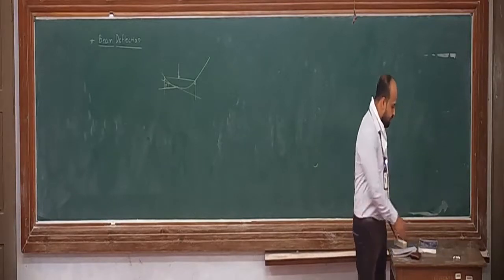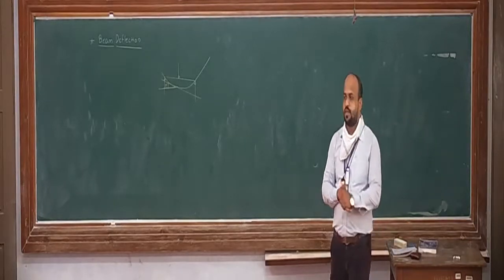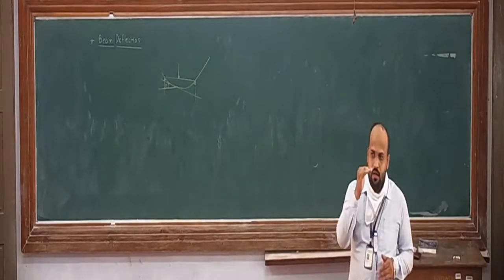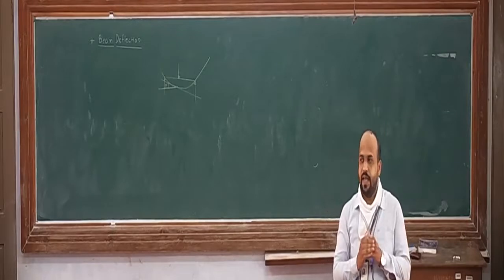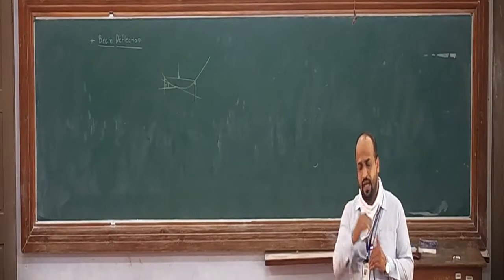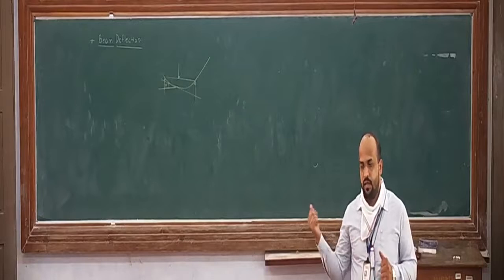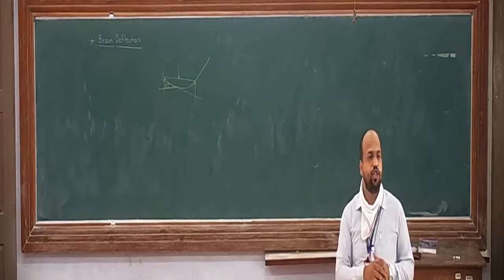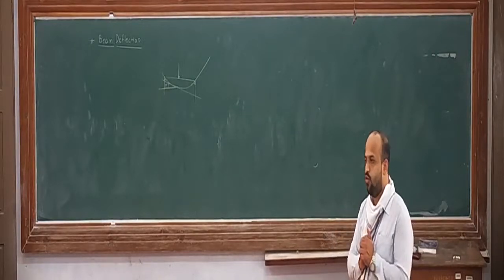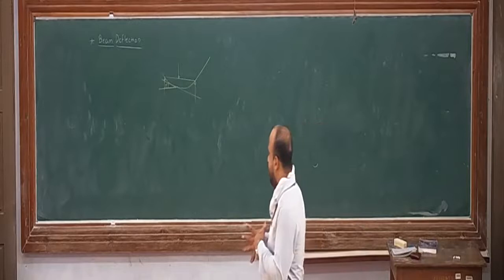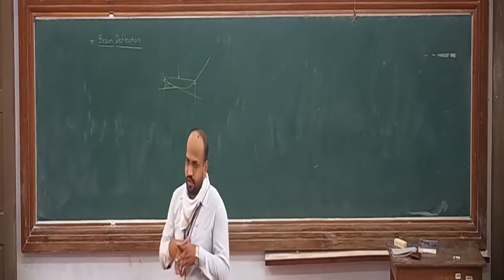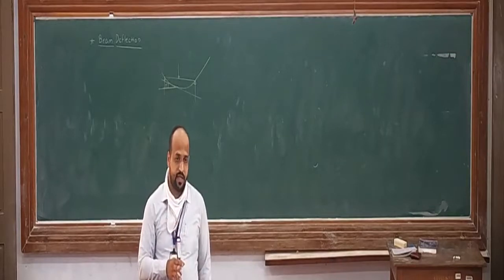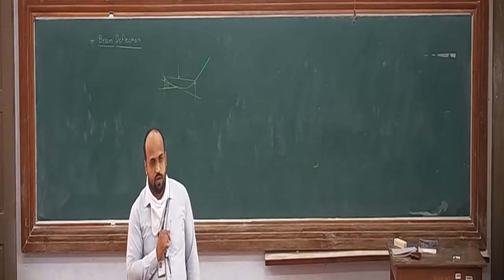Okay. So these two things are important for us because we need to get the deflection, which is nothing but how much a point on a beam has displaced, and the slope, the tangential angle at the point with respect to the longitudinal axis. These two things you need to know because we'll now be deriving the generalized deflection equation. We'll get one deflection equation by the double integration method, and that will be useful for you.